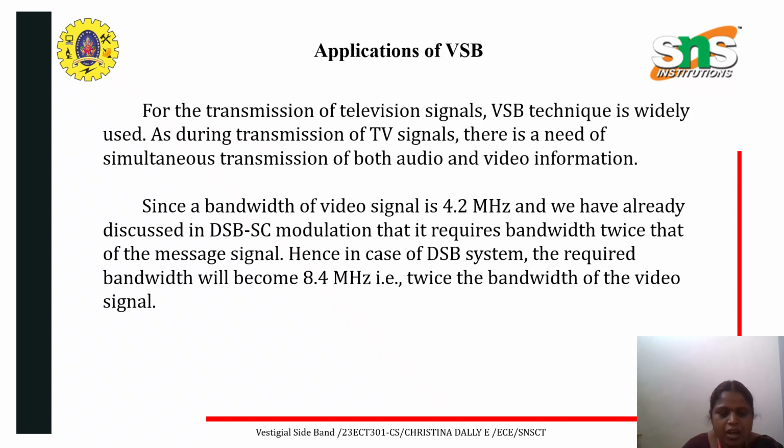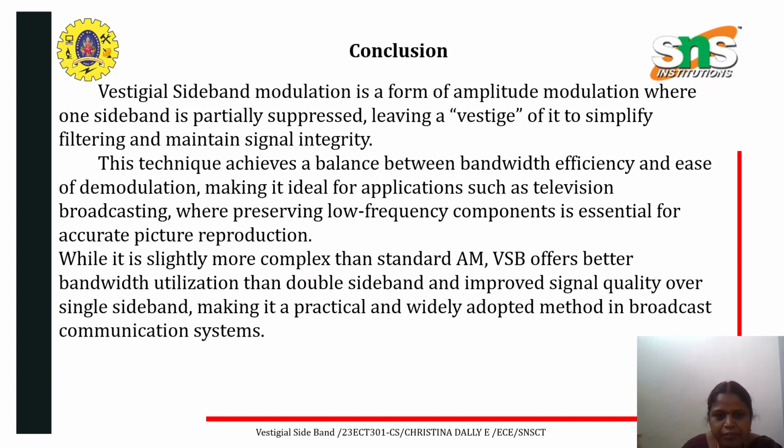Coming to the applications of VSB, for the transmission of television signals, the VSB technique is widely used, with simultaneous transmission of the audio and video information. The bandwidth of the video signal will be 4.2 megahertz, and multiplied by 2, we get 8.4 megahertz.